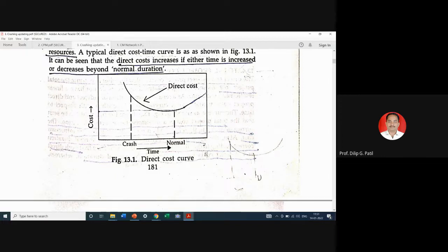So accordingly, unless and until 15 days are at least completed, or whatever it is, 28 days or 7 days minimum strength, the next activities dependent on or above that particular slab cannot start. It cannot happen that we have constructed or casted slab today and we have started our work tomorrow by adding more resources. So you will have to give the minimum time period required. So you cannot keep crashing beyond that particular limit.